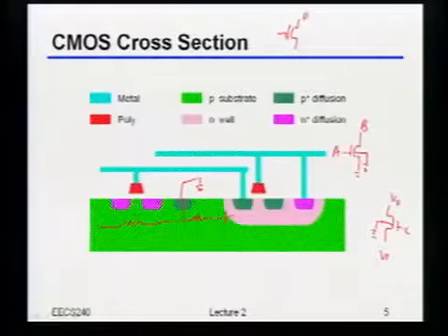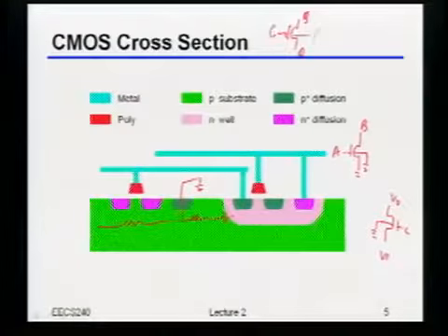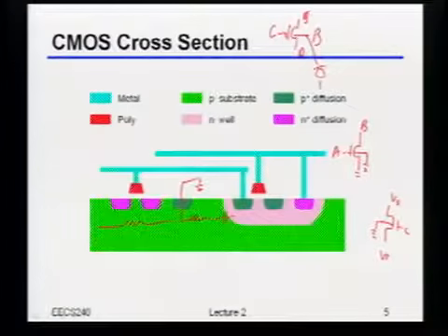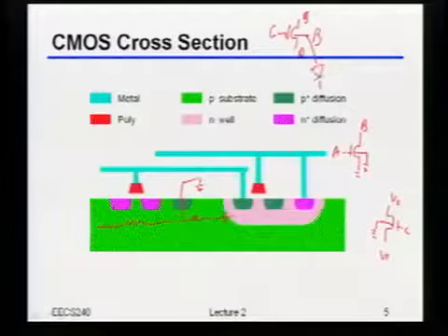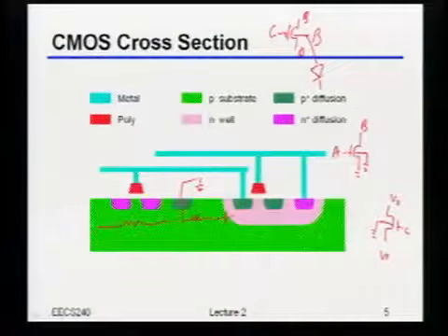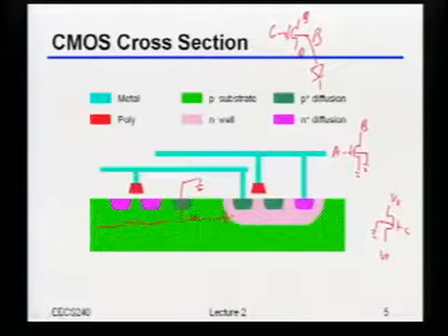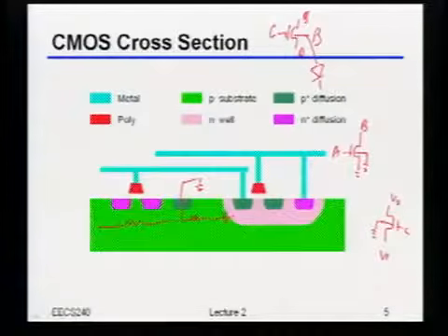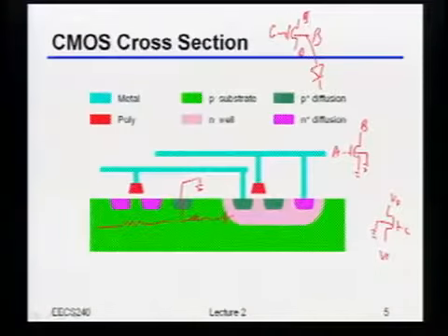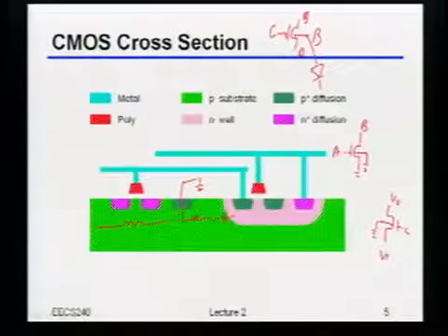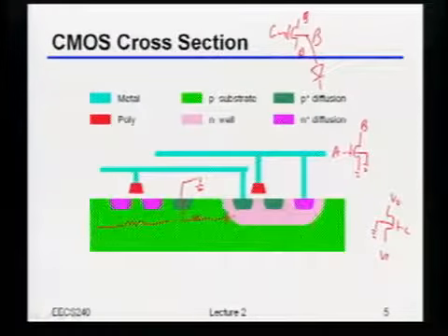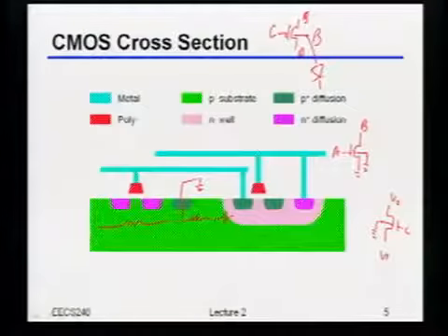So every time you put a PMOS, usually in SPICE, you just do something like, okay, I've got my 4 terminals, right? But in fact, there's almost always some diode sitting there. Oops, I drew it the wrong way. Basically, from the body to the substrate, right? Actually, I guess I drew that the wrong way, but you can figure that out, right? So basically, every time you instantiate a PMOS, there's actually extra stuff sitting there that SPICE is never going to handle. So again, point only being here, just pay attention, because sometimes that extra stuff actually is going to matter for the circuits that you're going to build.